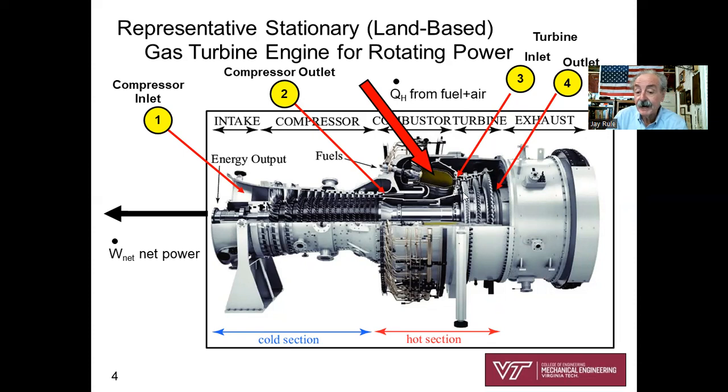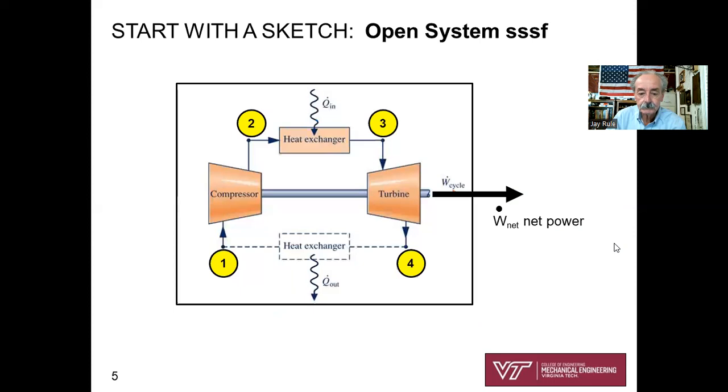Now that very hot air is going into, for this example, 1, 2, 3 stages of an air turbine. And so that's spinning the rotor. Much of the power is going to drive the compressor, but the excess power is going to drive the electric generator. And then out from this 3-stage turbine process is the exhaust gas. Hot exhaust gas goes out to the surroundings. So that's a general idea of the equipment associated with a stationary gas turbine engine.